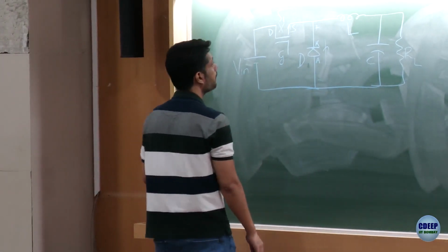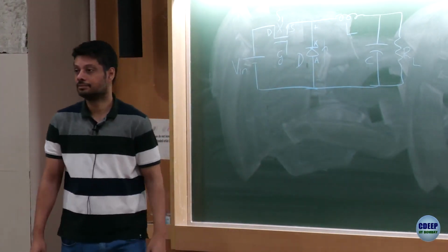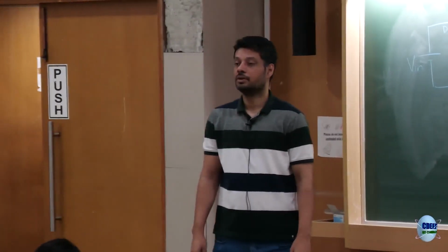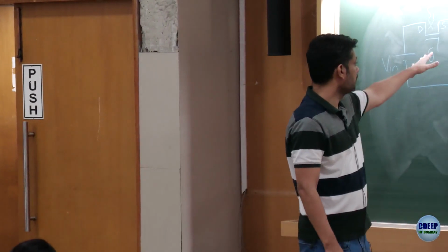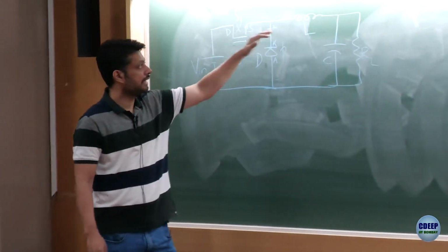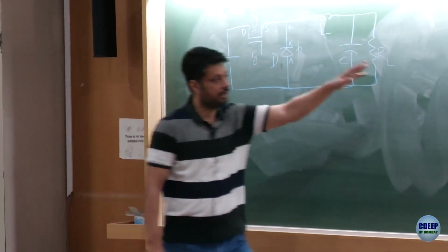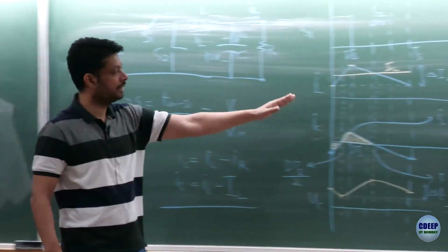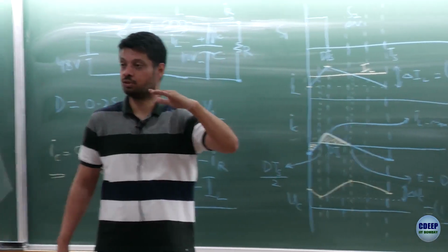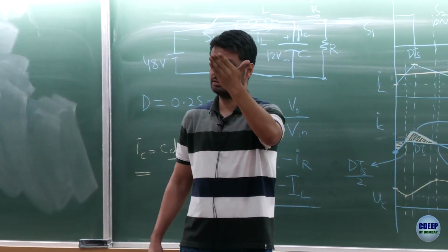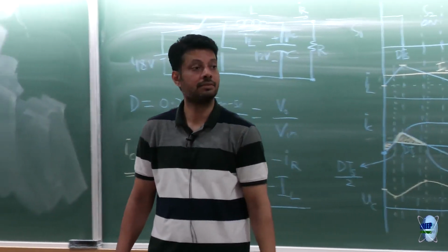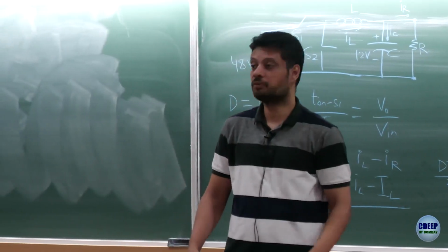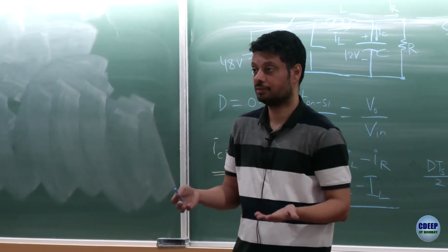What forces the diode to be turned on when the MOSFET is off? When the MOSFET is on, the inductor current rises, as it does here. Now when you turn off the switch, there is a positive inductor current, and that current will force the diode to turn on.